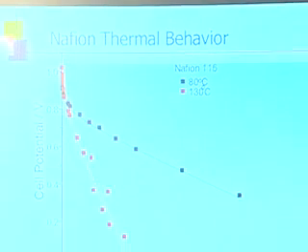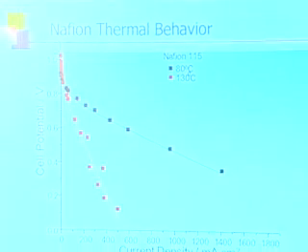What the cell won't do is generate significant voltage. So that 20 amps is being generated at somewhere around half a volt. And so to get the kind of voltage that one needs, you take a bunch of those and stack them together. That's a fuel cell stack. And the voltage, of course, adds because they're in series, and that's how we go. But all the data that I'm showing you, and this is what I showed you last time, is based on one of those single-cell membrane electrode assemblies, MEAs.